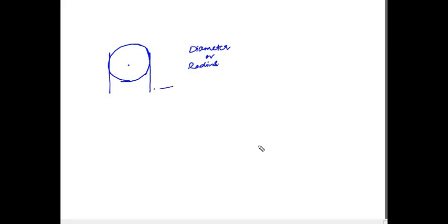So these are your extension lines now. Between these two we can draw the dimension line and then terminate with the arrowhead, and above that you will write, let us say this has a diameter of 30 mm, so you can write it as Ø30. Diameter is indicated by phi in the drawing. Wherever you see phi, it indicates diameter. Okay, this is one way of doing.